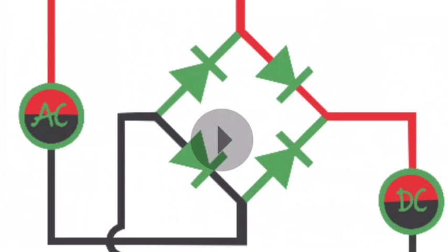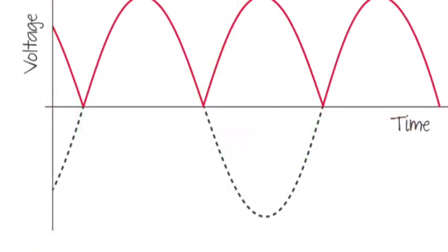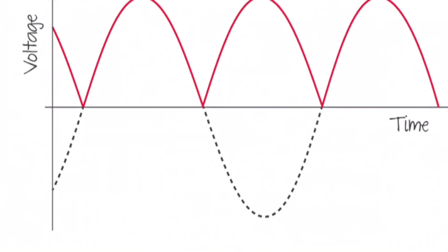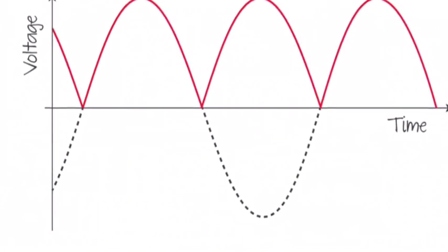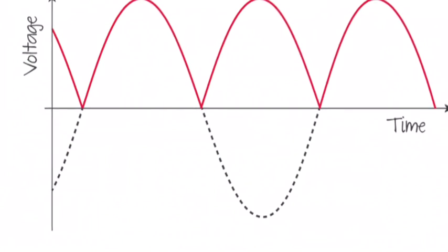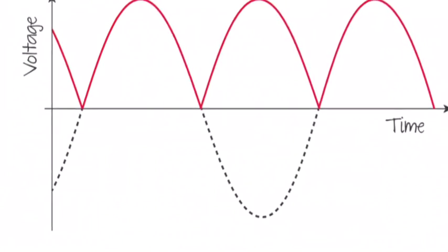Now, full-wave rectification. We saw half-wave rectification, but the most efficient way to pass AC to DC is to use full-wave rectification, as half-wave rectification divides the efficiency by 2, way too much, basically just 50%. Full-wave rectification uses a diode bridge, a more complex series of diodes that reverses the negative parts of the AC to give a series of positive peaks, but still not a constant DC output.